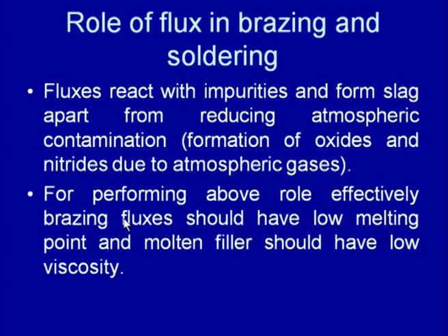For performing the above role effectively, the brazing fluxes should have a low melting point, and the molten filler metal should have low viscosity, so that things can react effectively. After removing these impurities present with the filler material, the filler material can get distributed uniformly between the fixed surfaces for developing the